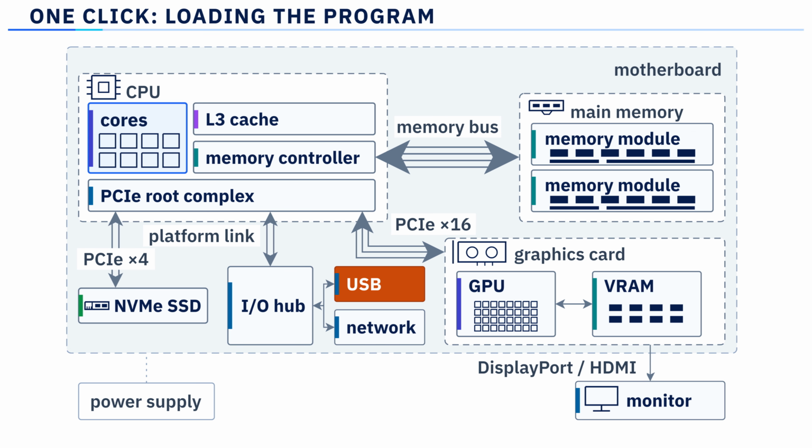USB is a family of standards, not one connector. Each device says what kind of thing it is, so the system talks to it through the right driver. The network interface sits beside the USB port. Your click came in over USB. A file you download would come in through here. Both reach the board through the same hub. That is why the hub is here. The CPU gives it one link, and it fans that link out into many ports, so you can attach more devices than the CPU has lanes for.